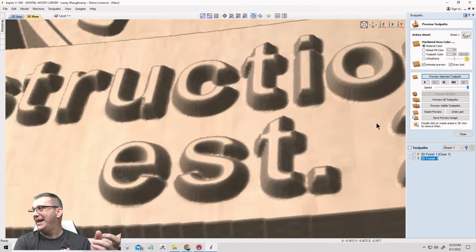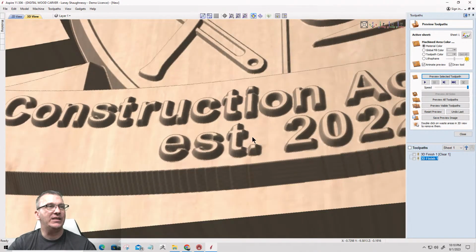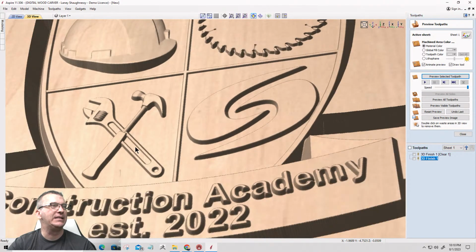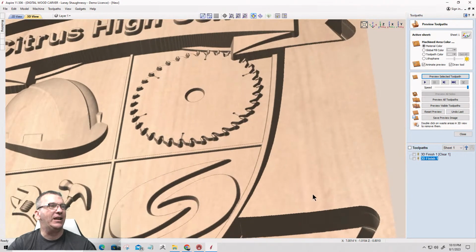But did you see that change from the 1/8 to the 1/16 inch bit? The cut quality difference. You see that the 1/16 was able to get in there and get that detail for that finer cut. Now, imagine, in this case, I really don't need to go to the 32nd. The 1/16 is enough for the detail of this particular design.